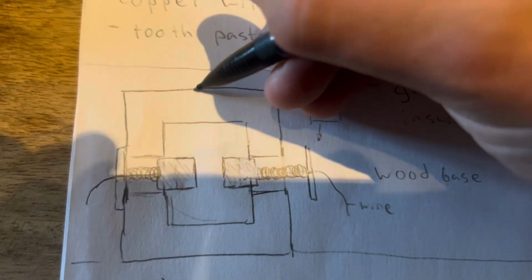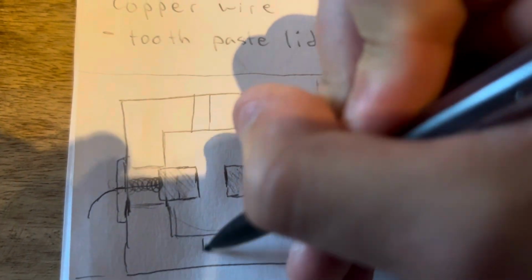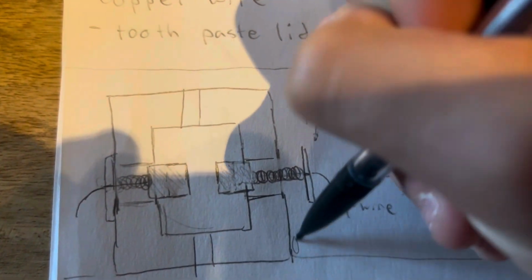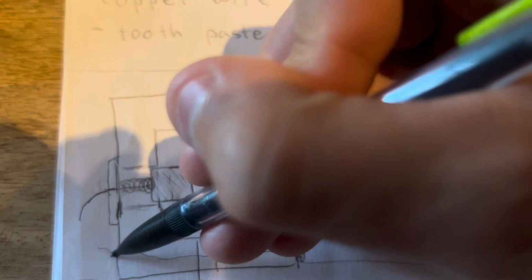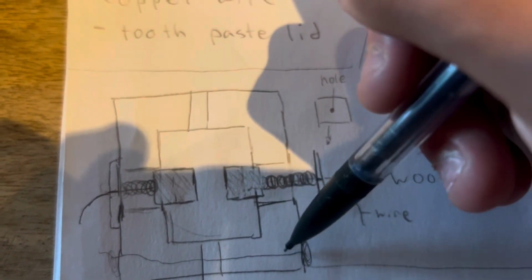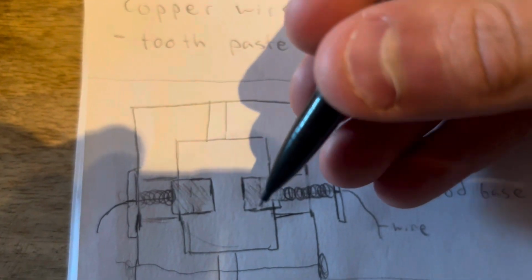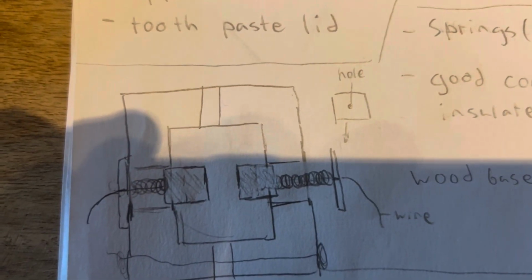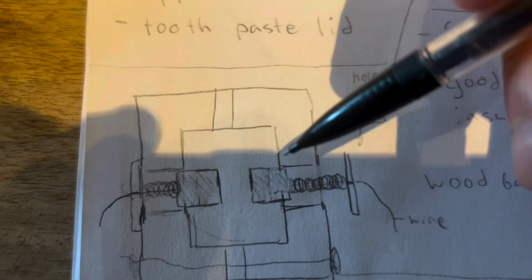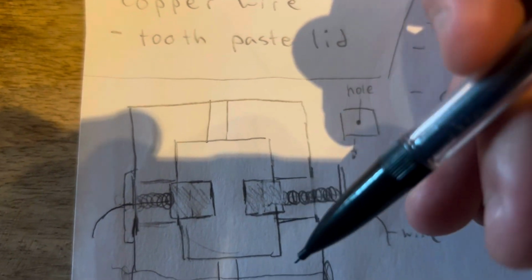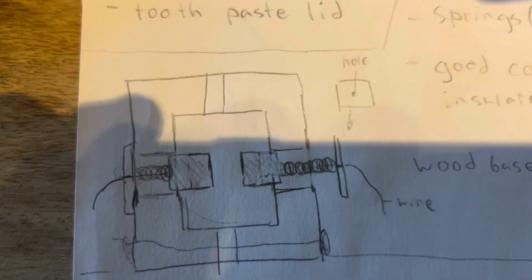Now, what I would actually do is leave a gap in here. Another thing I saw is you would have something like a screw here going all the way through, maybe a screw here, so that you could tighten and loosen these. Because if you had too much friction caused by these brushes, you could just loosen the screws a bit, and then your motor would get going. And let's say the brushes got worn out, because they do, and your motor stopped working. Just tighten the screws a bit, and then your motor could keep going.